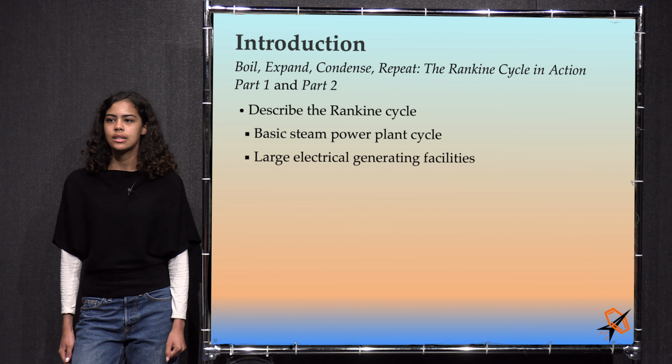At 44 degrees Celsius and 0.091118 bar, we have V hat of the liquid is 0.001 and change cubic meters per kilogram. H hat of the liquid is 184.26 kilojoules per kilogram. H hat of the vapor is 2580.7 kilojoules per kilogram. The S hat of the liquid is 0.62547 kilojoules per kilogram Kelvin. And the S hat of the vapor is 8.1816 kilojoules per kilogram Kelvin.